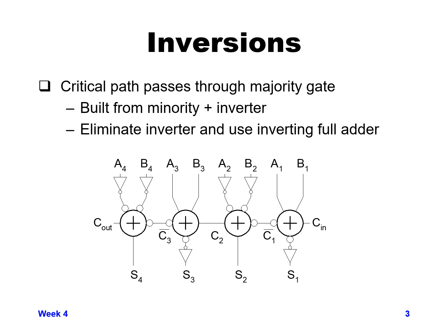If you remember the designs of adders 1, 2, and 3, when we're not talking about the full dual-rail domino design, in each of those versions, if you had a C in coming in, you would get a C out bar. For a fast stage, if you just do a single stage of complementary CMOS, every stage is typically inverting. So when you have a C in, you get a C out bar, and you have to add an extra inverter to get C out non-bar.